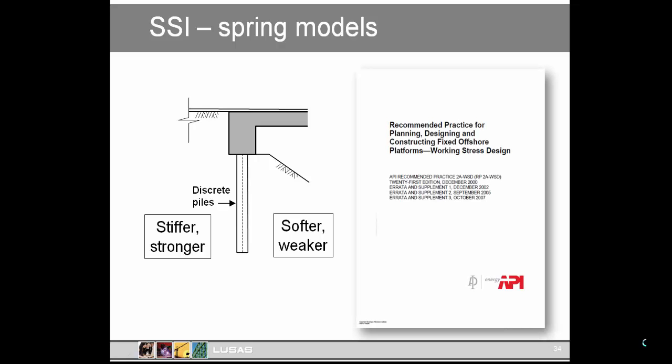This API publication brings together methods for defining load deflection curves for laterally loaded piles appropriate to various soil materials under static or cyclical loading, and I'd recommend it. Comprehensive software should be able to handle the nonlinear PY curves, which also change with depth.